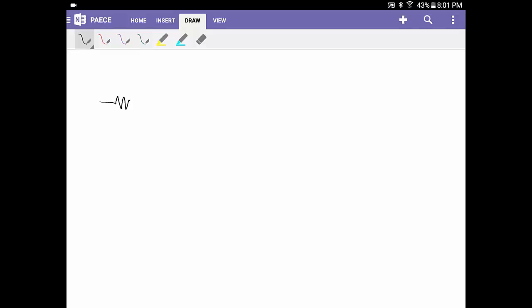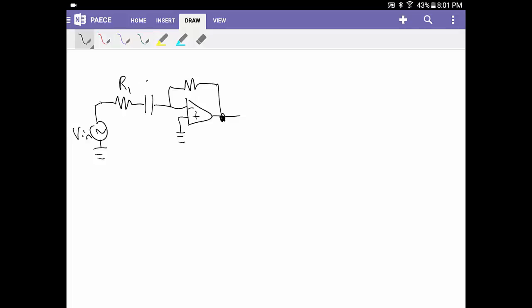And remember, we want to use our limited versions because we don't want things like noise to get extremely amplified, or all these DC terms to wash out any signal that we want. So let's have our input signal V in. Let's just say R1, C, R2 into a low pass filter, and this will work. Albeit it looks a little sloppy, but this works. However, I would like to say, here's V out.